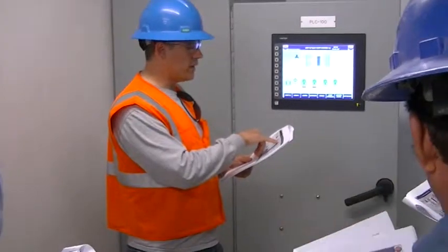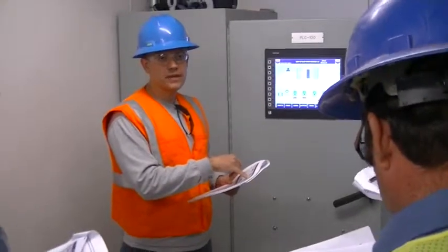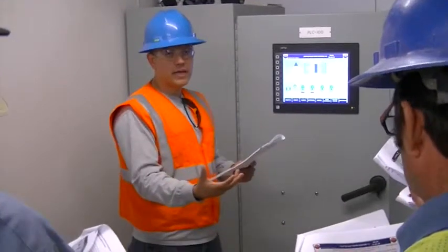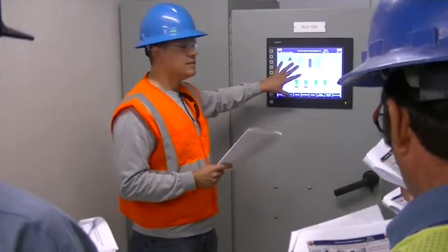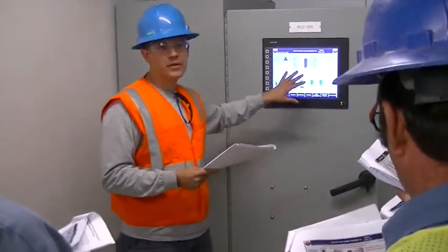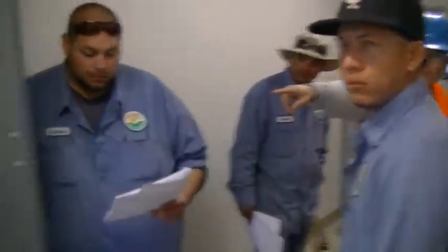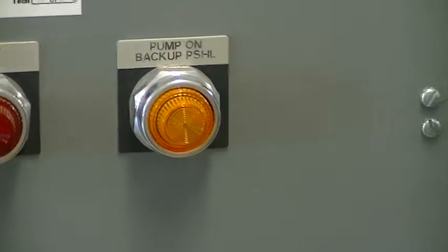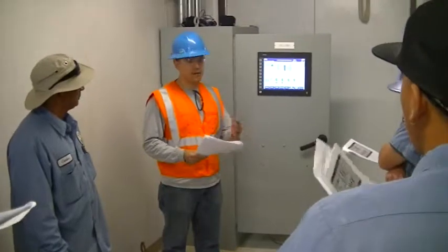The discharge pressure analog fail. That's what's controlling your boosters, that discharge pressure out there. If that fails, if you lose signal from that, it's going to lock that out and put this into what's called backup PSHL mode. You can see over here the amber light on the VFDs that says backup PSHL, that means it's going to be working off the Mercoid switches. At that point, the PLC is pulled out. It's no longer in control. Everything's being controlled by those Mercoids because that pressure switch failed.